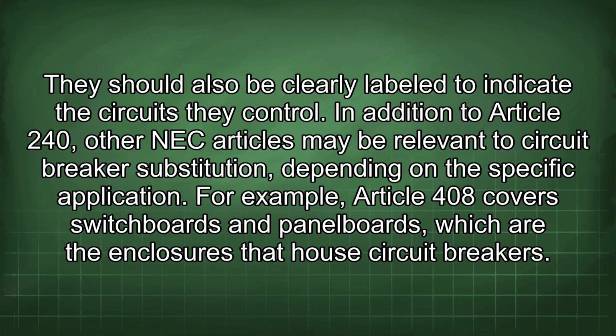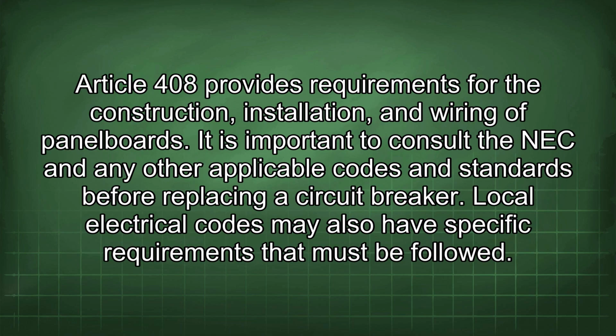In addition to Article 240, other NEC articles may be relevant to circuit breaker substitution depending on the specific application. For example, Article 408 covers switchboards and panel boards, which are the enclosures that house circuit breakers. Article 408 provides requirements for the construction, installation, and wiring of panel boards. It is important to consult the NEC and any other applicable codes and standards before replacing a circuit breaker. Local electrical codes may also have specific requirements that must be followed.